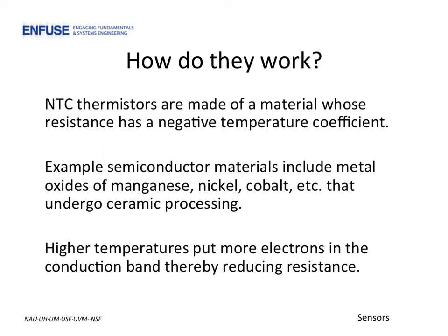So how do thermistors work? As noted, there's a negative relationship between temperature and the resistance in an NTC device. Another way of looking at this is as temperature increases, the conductivity of the device improves. This is a characteristic of the semiconductor material that is used to make the device. As the material gets warmer, more electrons make their way to the conduction band, thereby reducing resistance. These materials tend to be metal oxides that have undergone some ceramic processing.